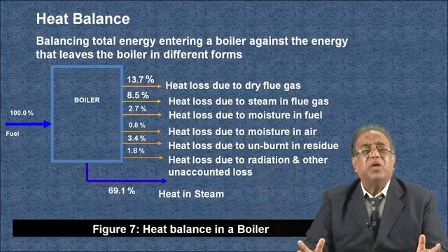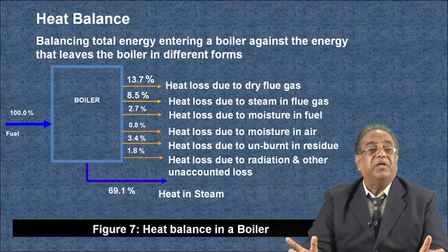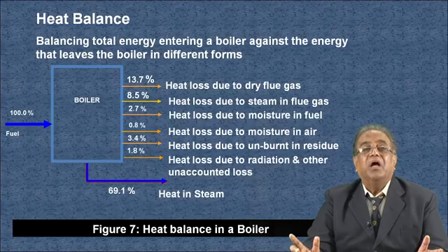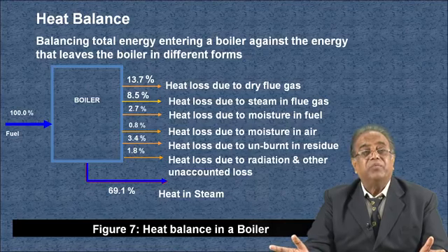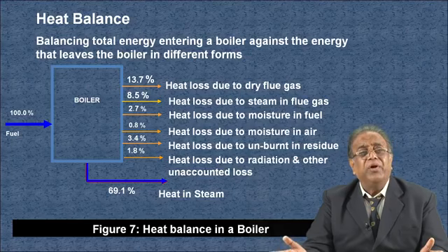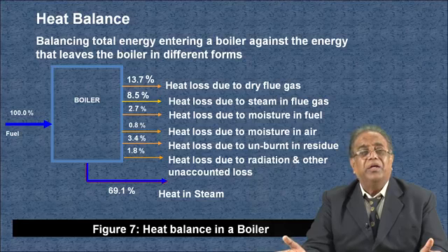For this case we have considered 13.7% as the heat loss due to dry flue gas, 8.5% heat loss due to steam in flue gas, 2.7% heat loss due to moisture in fuel, 0.8% heat loss due to moisture in air, 3.4% heat loss due to unburnt in residue, and 1.8% heat loss due to radiation and other unaccounted loss.